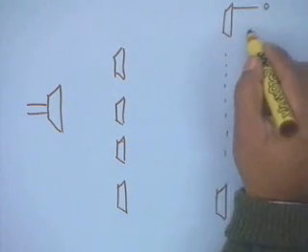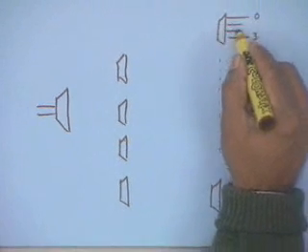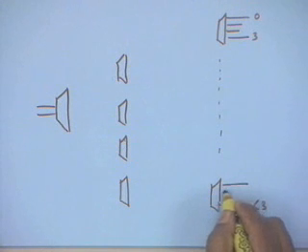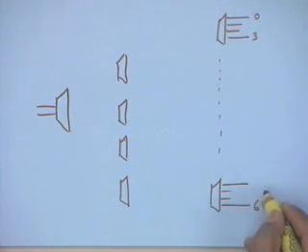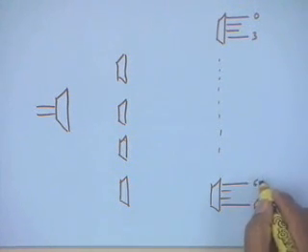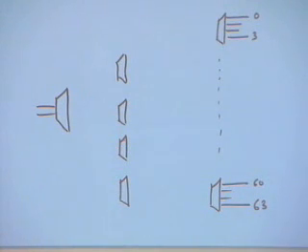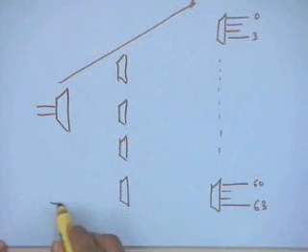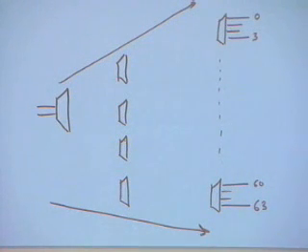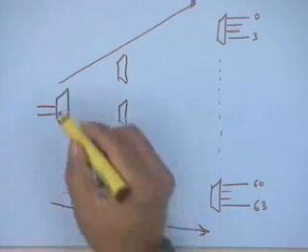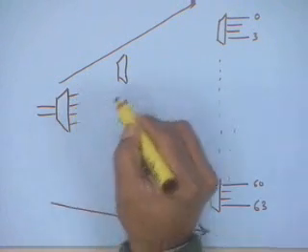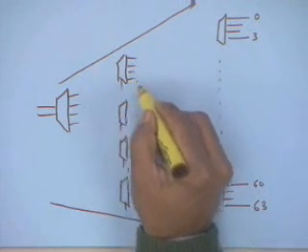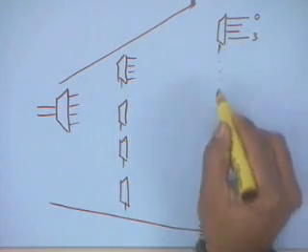So 0 output comes from here, 3 comes from here, and then 63 comes from here, and so on, 60, 61, 62, 63. And the reason it's called a tree decoder is the fact that it's growing like a tree. So this particular output of this is going to enable these, and output of these is going to enable these, 4 of them.